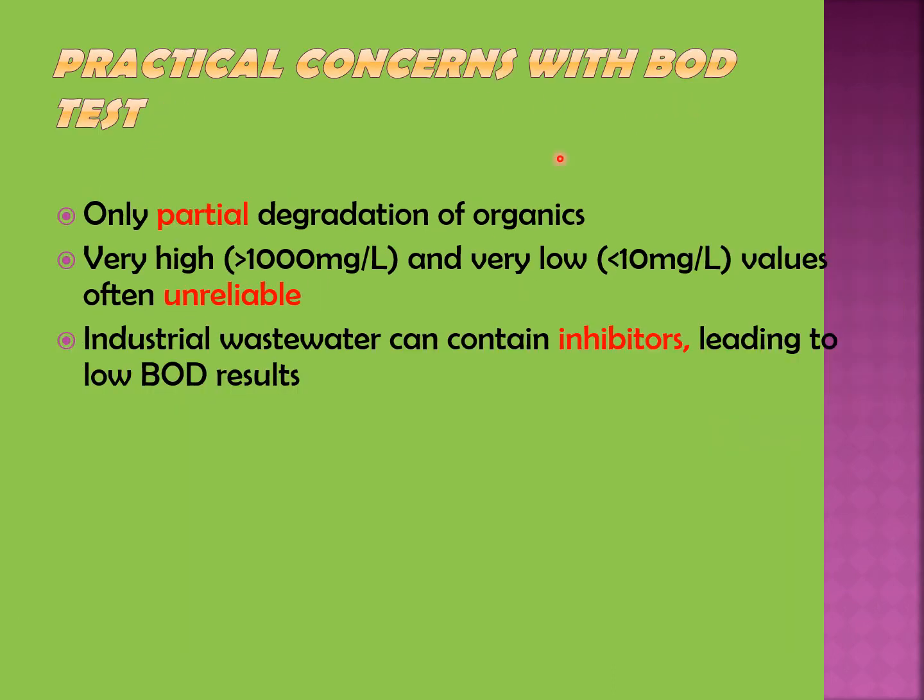Practical concerns with the BOD test. The BOD test degrades only partial organic matter. The test results will be unreliable when the BOD load is greater than 1000 mg per liter or lower than 10 mg per liter. Industrial wastewater can contain inhibitors, leading to low BOD results.